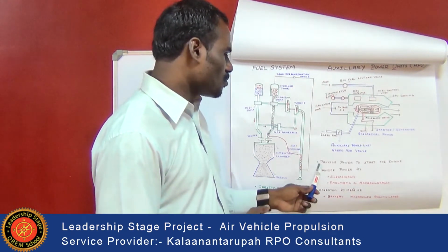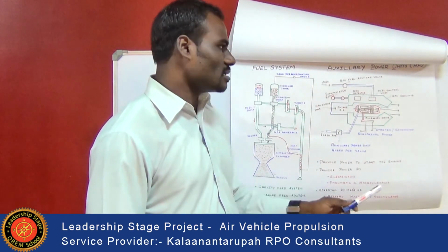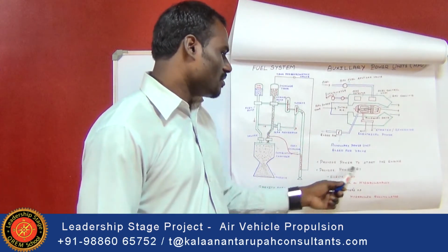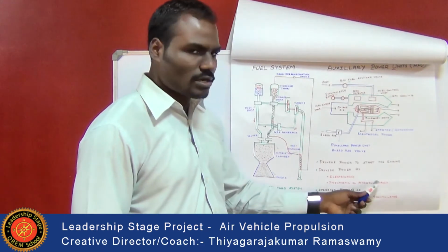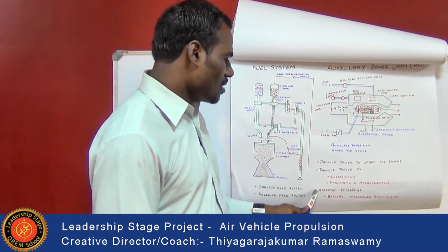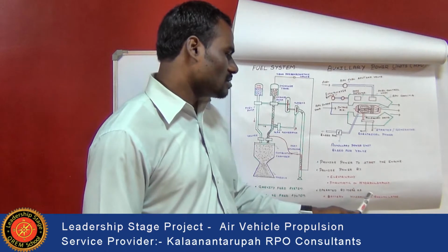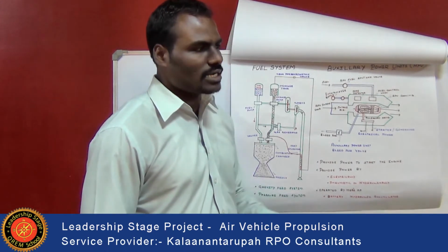Here it provides power to start the engine. The auxiliary power unit provides power to start an engine, and it also provides power to the electrical, pneumatic and hydraulic systems as well. It is operated by means of a battery and a hydraulic accumulator as well.